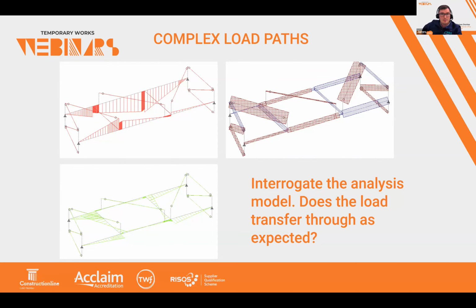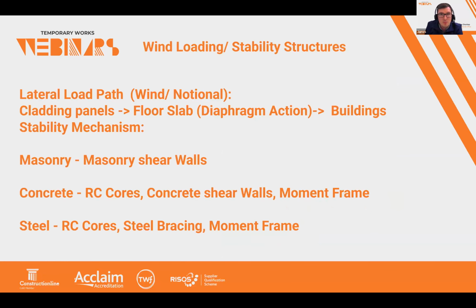and deflecting correctly. I'm going to bring up briefly wind loading or instability of structures. So if we're applying a lateral load to the structure, so wind or notional, typically we're applying wind loads to cladding panels or walls, that will be transferred to the floors of a structure, and then through diaphragm action it will be transferred back to the stability mechanism for the structure, which for a masonry structure we're typically talking masonry shear walls.